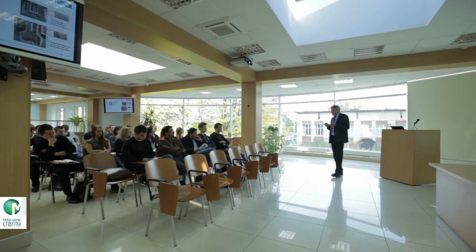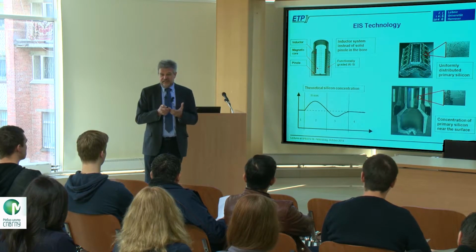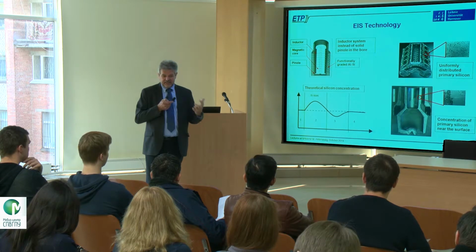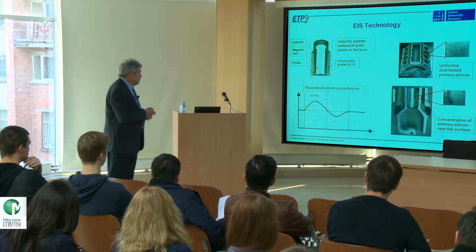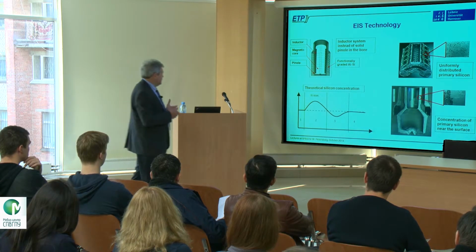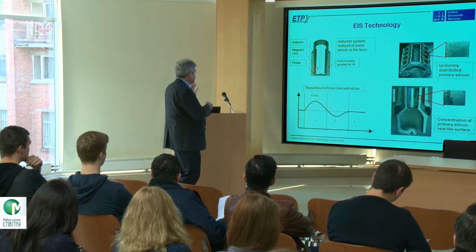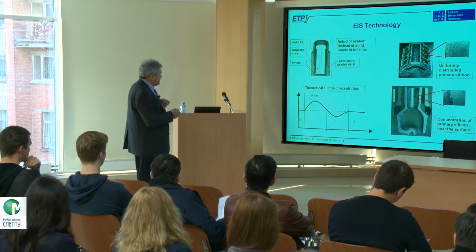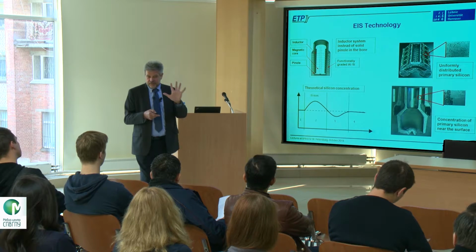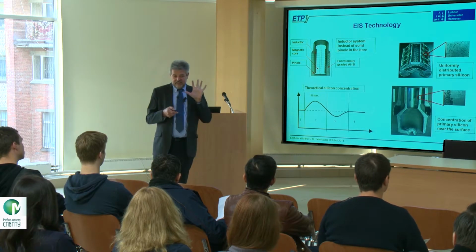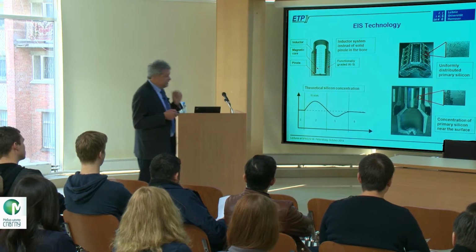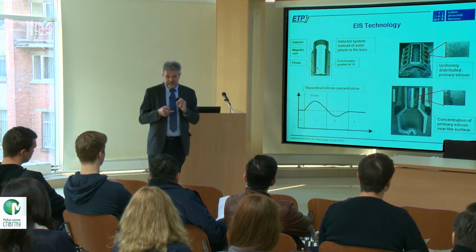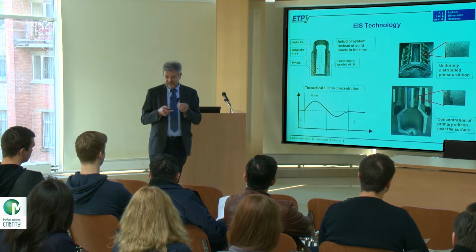There is, of course, one effect of electromagnetic fields, the Lorentz forces. The Lorentz forces act on materials which are electrically conductive. So if, during the melting of the material, you use an inductor like this one, the inductor generates Lorentz forces, which press away the aluminium. Lorentz forces always tend to press away from the coil. So it presses away the liquid aluminium. But silicon is a low conductive material, so Lorentz forces are very small, nearly zero.